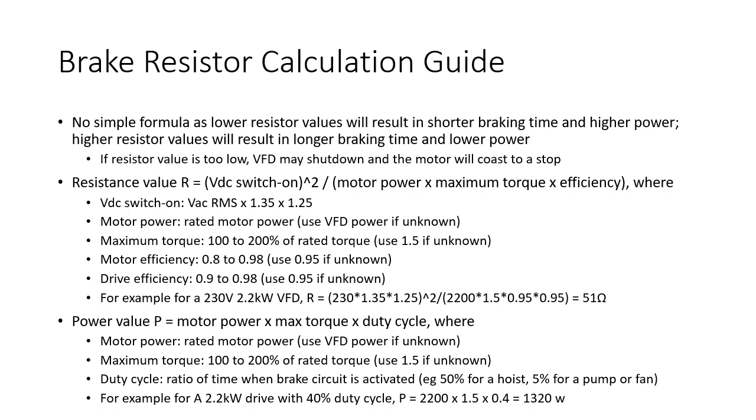Now that's quite a low value for a resistor. So we also need to calculate the power value, because we're going to need to know how much power that resistor is going to dissipate. If we get the power too small, then the resistor will just be destroyed in a small time. If we get the power too big, then that's less of an issue, except it means it's a bigger unit and it costs more.